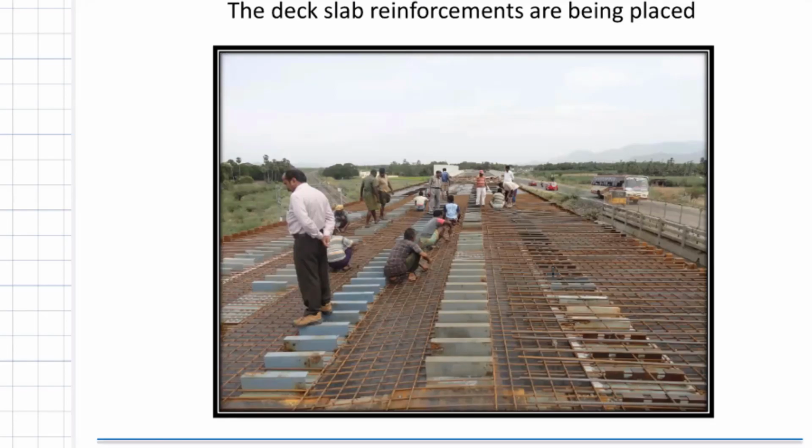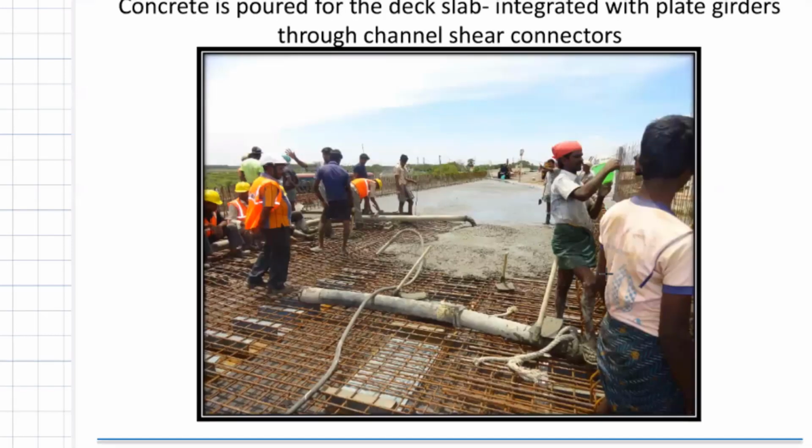So it is always better to design a steel concrete composite action so that you utilize the best of concrete and the best of steel. Because otherwise, you can take the entire concrete load as a load to be carried by the plate girders, and we put minimum shear connectors, right? After that, concrete is done, very easy. I always say concrete is poured like water, then you can fill it up, right?